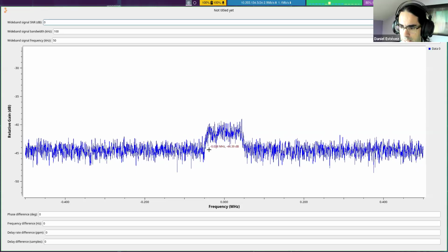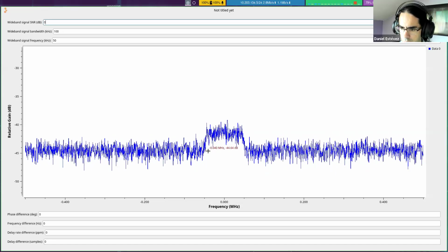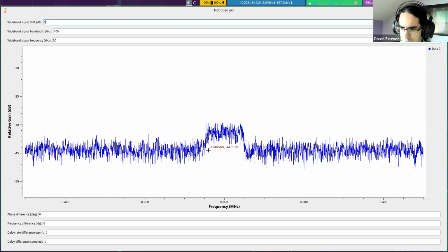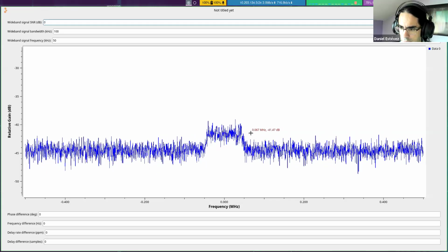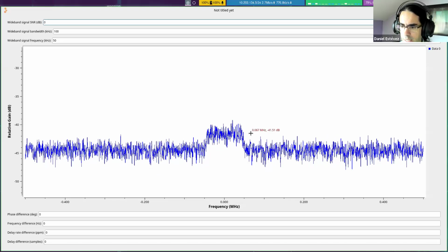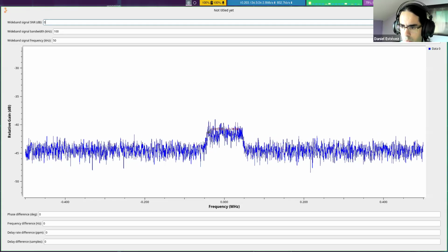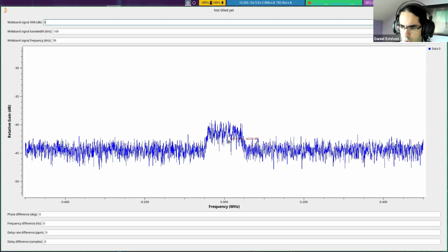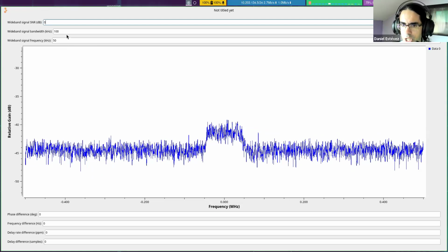And do we get something like that? We should. So the noise floor is at about minus 44.5, I would say. And this should be minus 41.5, and it is. So that's what makes it very easy to understand what's going to be the power of this noise in comparison with the power of this noise floor, even if we change the bandwidth.